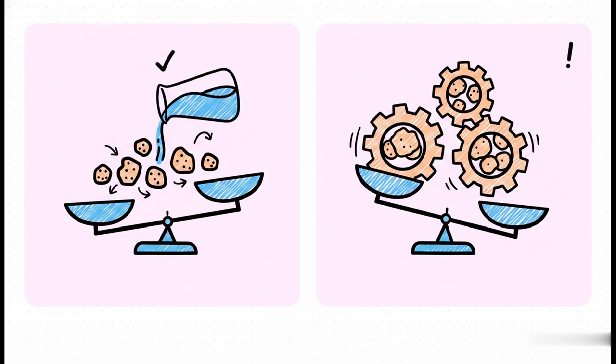On the plus side, lower viscosity and lower surface tension mean your liquid flows like a dream. It gets into all those tiny gaps in your pigment and massively speeds up the wetting phase. Sounds amazing, right? But wait. On the flip side, that lower viscosity completely destroys the shear stress in your mill.